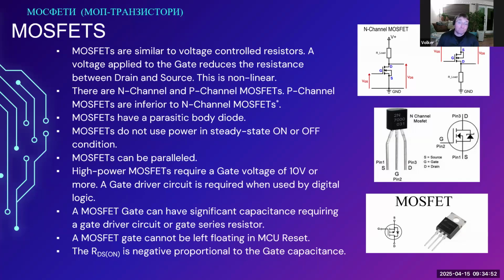And they work. So I can't really complain about that. I can complain about other items. The current rating on those motor controllers is sometimes absolutely ludicrous because they don't have any heat sinking capability. But that is a totally different item that we might talk about later. They have a parasitic body diode. So even if it's not in the image, it is there.